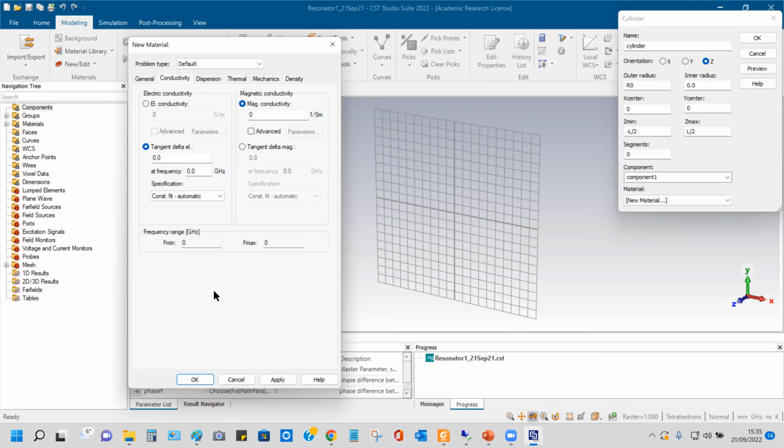Many papers are appearing. And if you talk in terms of, for example, transmit array or reflecting properties or transmitting properties, ultimately what you're doing is beam steering, whatever you want to do. You are playing with the effective epsilon, thereby the frequency or amplitude and phase, and also the L and C. All these parameters are getting affected. Therefore you can play with the wave that is propagating within that structure, so you can control the beam as well. So all boils down to that only.